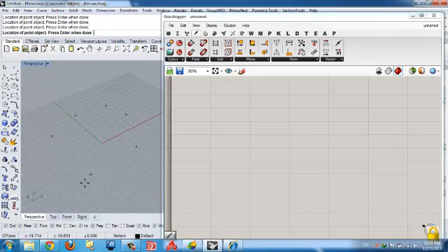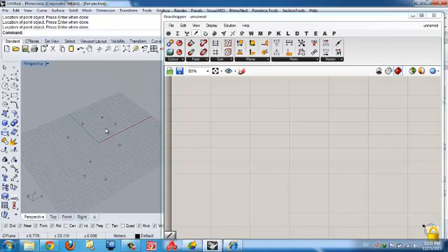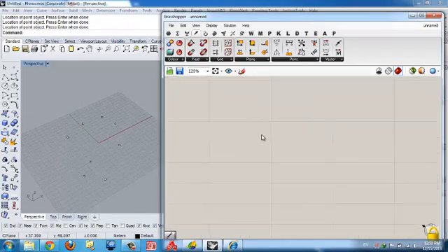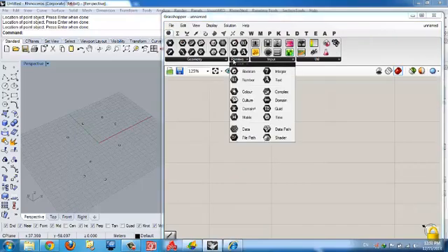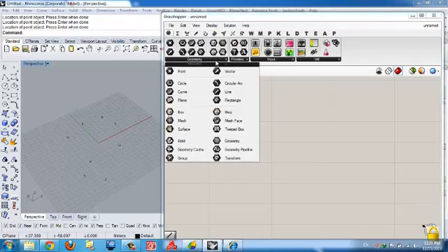Here we have some points, and we want to import them into Grasshopper so we can work on them or have different things. So I just go for the params, and here we go. These two places, the geometry and the primitive, are where you can choose what you want. For example, you want to import a point or a vector or anything geometrical, you can go here.